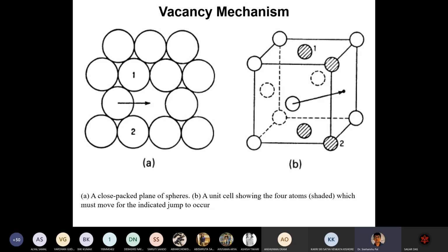The reason that iron diffuses so much more slowly than carbon is that each carbon atom always has many vacant nearest neighbor interstitial sites. Then the fraction of vacant iron sites is very small, and each iron atom must wait a very significant amount of time before a vacancy becomes available.